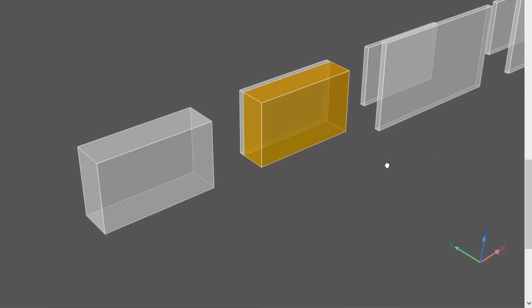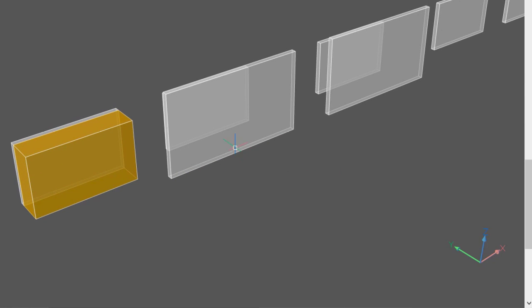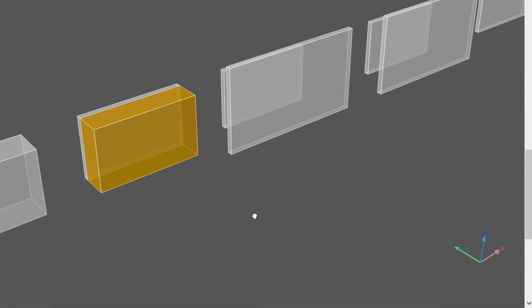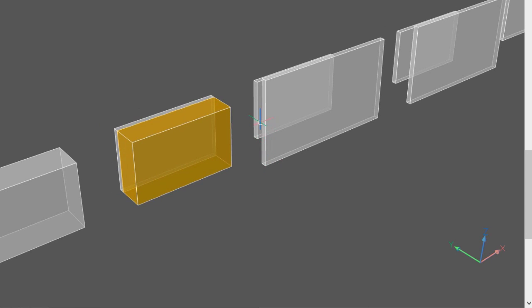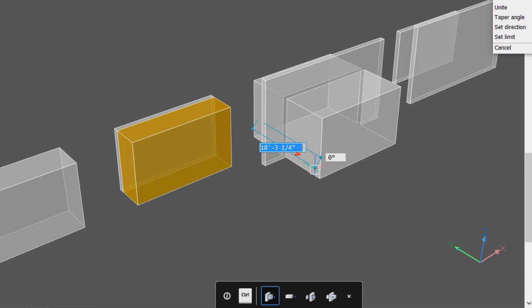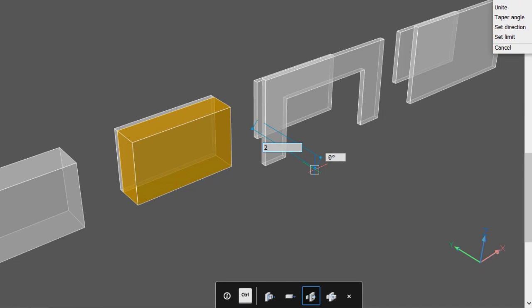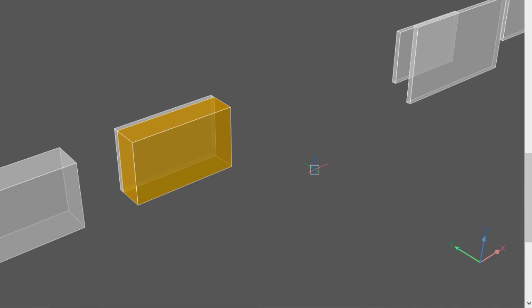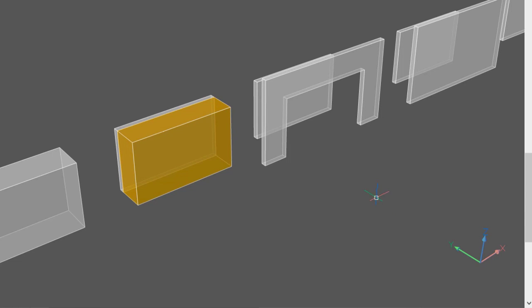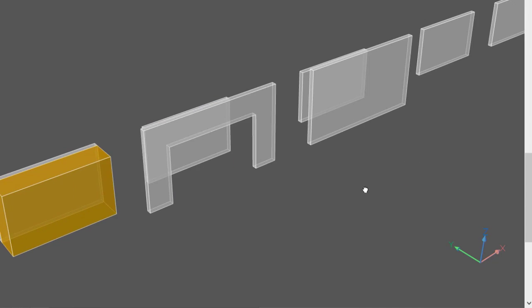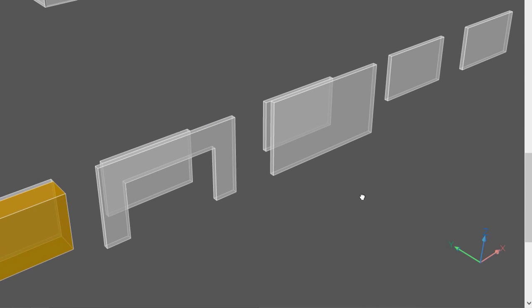The third option is about what happens when the extrusion engages other geometry, so two walls are shown. Selecting the smaller wall surface, choosing Extrude, hitting Ctrl twice, and specifying a distance, the result is that a void has been created in the second wall of the outline of the original surface, since the depth went all the way through the wall.